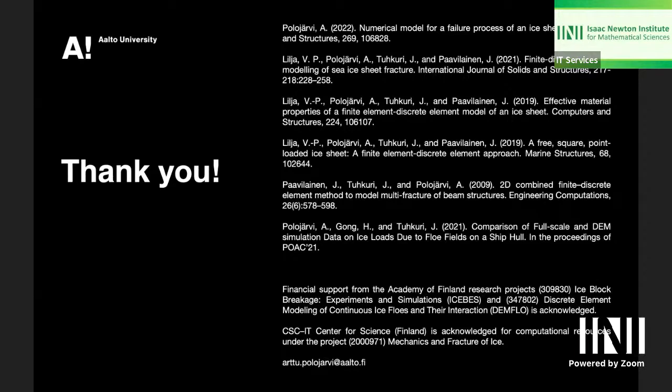And that's one of the reasons why you need to have some sort of damping in your model always. And that's of course very difficult to measure, what kind of damping I should use. But if I don't do that, then I'm just going to have stress waves traveling all around the place, and whatever time step I would use, they would eventually end up breaking the ice sheet, I think. But yeah, time steps are small, definitely.